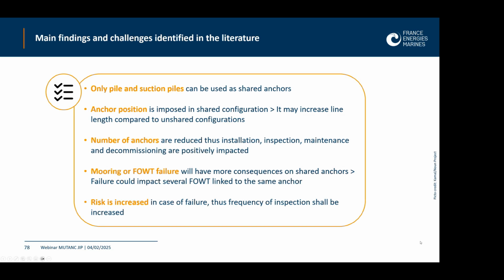So first, for the main findings and challenges identified in the literature. What we found is that only pile or suction piles can be used as shared anchors, as there is multi-directional loading. The anchor position is imposed in shared configuration, so it may increase line length compared to unshared configuration. The number of anchors is reduced. The installation, inspection, maintenance, and decommissioning are positively impacted.